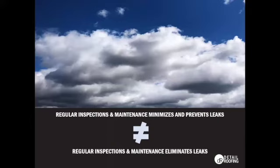So one thing that we do want to stress is regular inspections and maintenance can minimize and prevent leaks. However, we do not want you to think that we are saying that regular inspections and maintenance eliminates leaks. Unfortunately, nobody out there is going to predict all the leaks that are going to happen in your building, where they're going to come from, and get ahead of them before they happen. But the best chance of preventing and minimizing them is through regular inspections and maintenance.